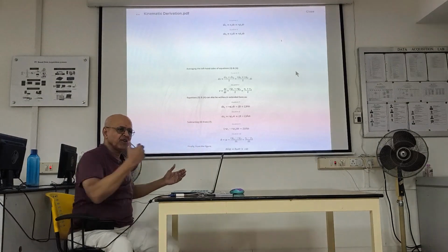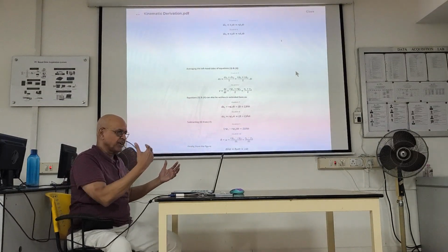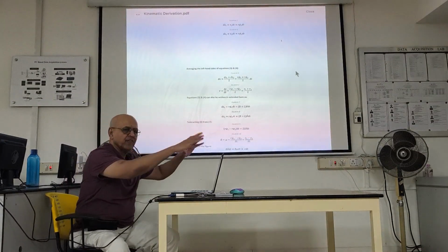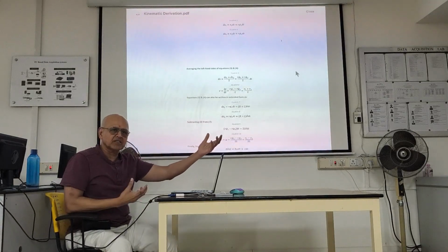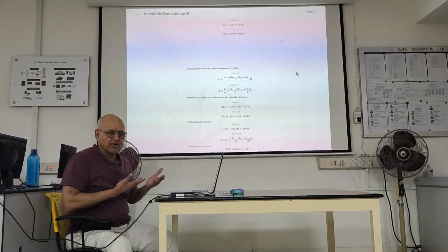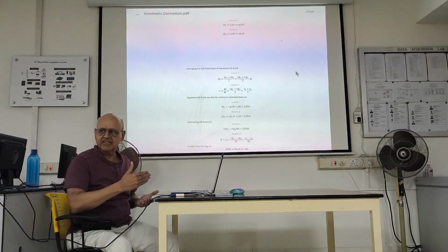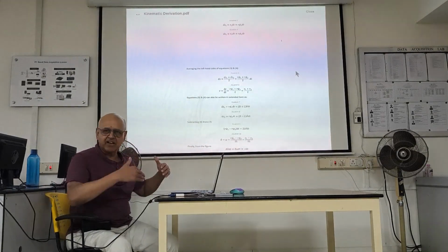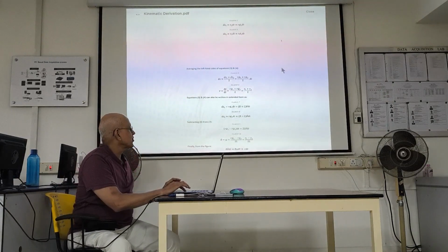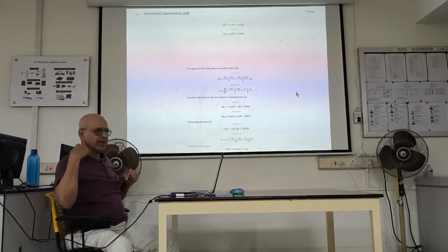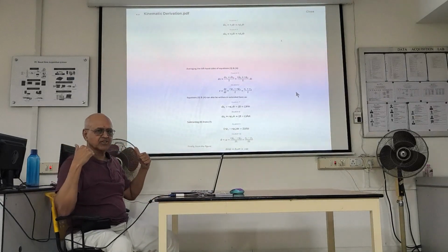Will you put it forward or will you put it back? Because if you put it back, then you can't load the front because you might tip over, right? So sometimes people use two caster wheels to provide uniformity. But that will be a pretty odd vehicle, right? A circular vehicle going through the airport. So typically, those vehicles are made triangular. So it's like this with one caster wheel. You can put two caster wheels in the back also.